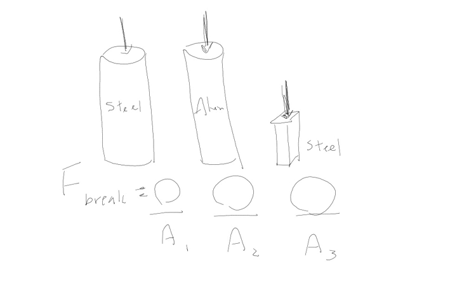If I take the three stress values now and compare them, how do you think they're going to compare? The first stress value for this large steel column is going to be much larger than the stress value for that aluminum column, because the force in the first column was much larger than the force in the second column, but their areas were the same. How about if I were to compare stress in that first steel column to the stress in that second steel column? Here's the great thing: if you were to make that comparison, these two values will be exactly the same.